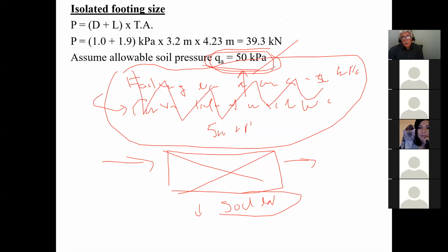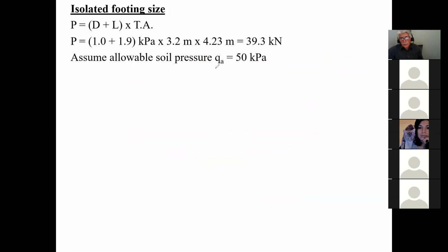So whatever you assume here, if you're going to be actually doing this in real life, you're going to have to make sure that you twist your client's arm, spend the money, get the soil tested. As a matter of fact, have the soil tested even before you do your drawing. This way you already have the information and you can do it without any assumptions, and then you'll be able to do everything correctly. A lot of people don't like to spend the money, and unfortunately you end up getting the problems.